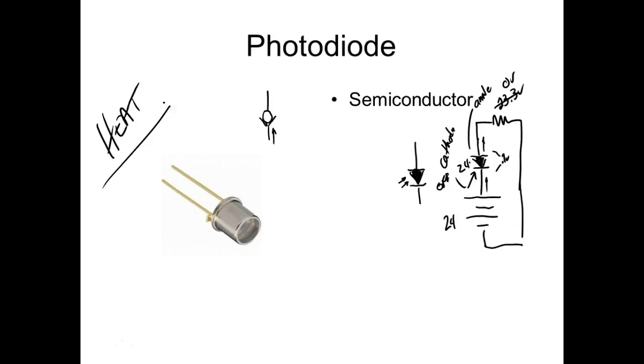Now that's nice. You can go out and buy an electric heater, right? You might have an electric water heater at your house, and that's all it's using those resistors for: to generate heat. But if you snap off your microwave oven and look at that electronic control circuit, you're going to see a lot of resistors on there, and those are not in there to generate heat. They're in there to bias those solid state devices to set the operating parameters of the device.